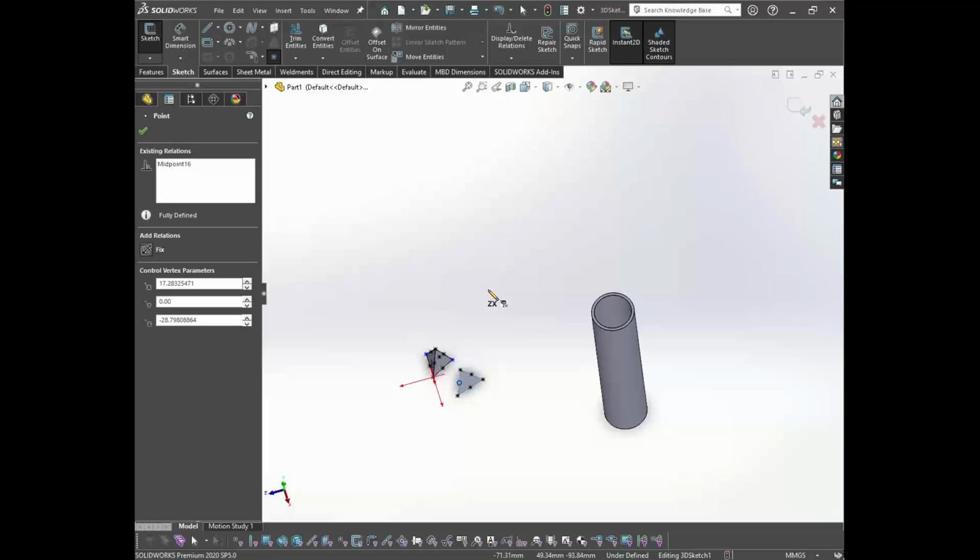So this will give you an idea about how you can design better prior to manufacturing. It may happen that you have designed a certain bracket, you are applying mild steel to it, so the yield strength is almost 350 MPa, and you are not performing any kind of FE on it, so directly you are sending it for manufacturing. So what happens when it comes to the manufacturing phase, and after applying the loading and operating for some time, it fails? The designer who has not used FEA prior to manufacturing can't tell why exactly it is failing, right?